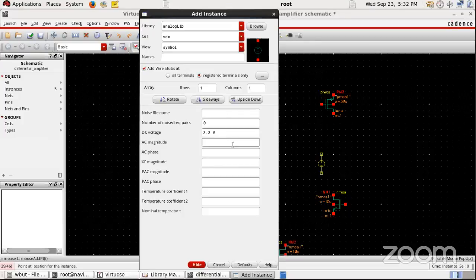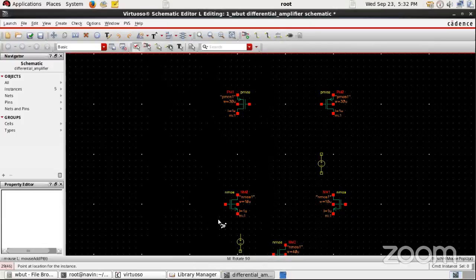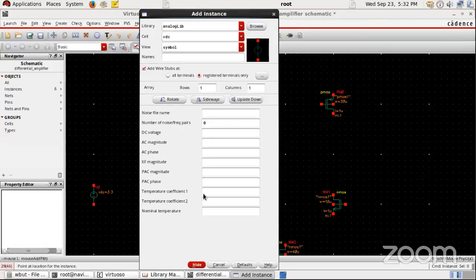That is why we have a differential input and differential pair, right? And we have two modes of connectivity, single-ended and double-ended. Okay, so supply voltage is 3.3 volts. So I'll get it here. And the bias voltage is, as we have already calculated, 685 millivolts for the NMOS pair.